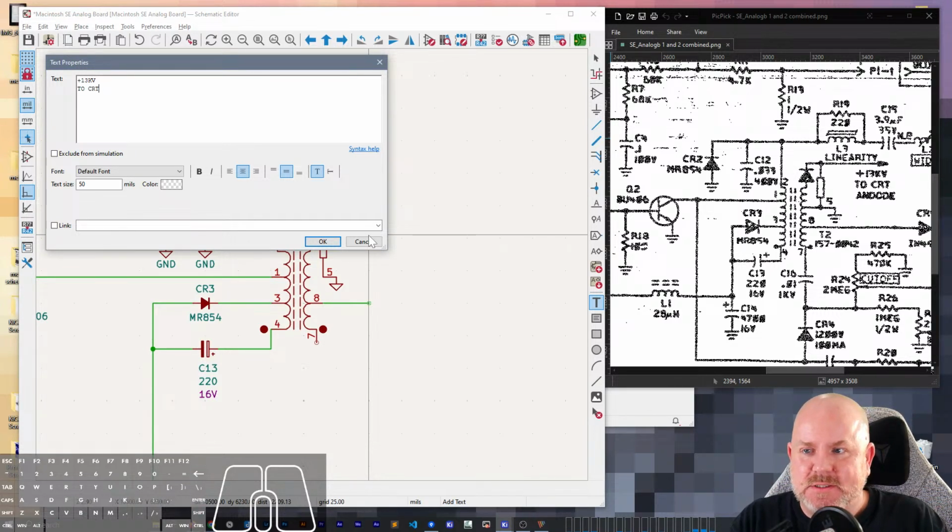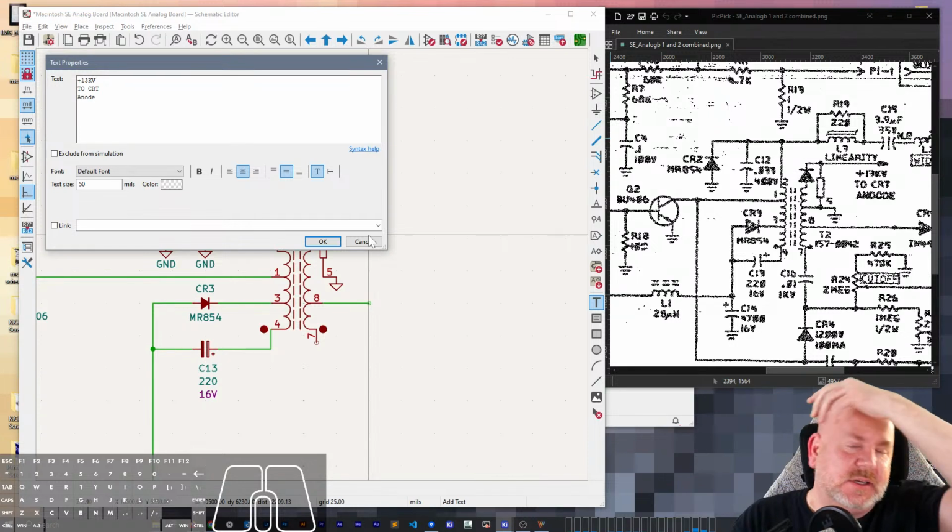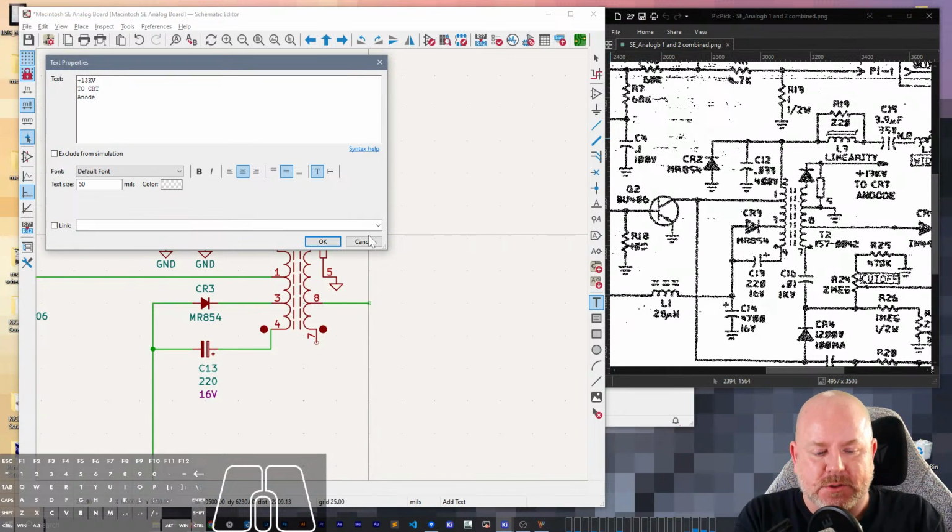There was one time I was desoldering the shield from a Commodore 64 board. The Commodore 64 has its EMI shield on the bottom of the PCB with little tabs that come up around the side and then solder onto the ground plane. So you have to heat up those little blobs and bend the tab. I did that one time, and my iron slipped, and it caused the blob to go flying, and a little bit of solder hit me right here in my cheek. In that case, I was wearing my glasses. So even if it had hit my eye, I would have had some protection.